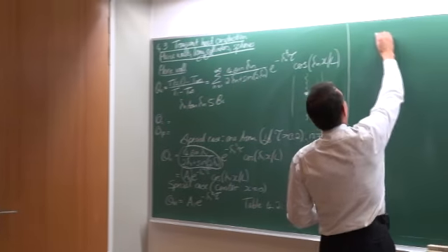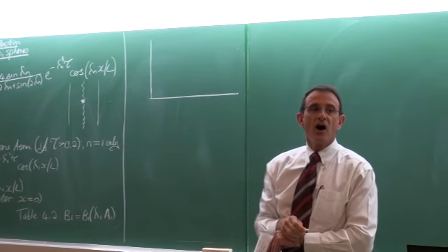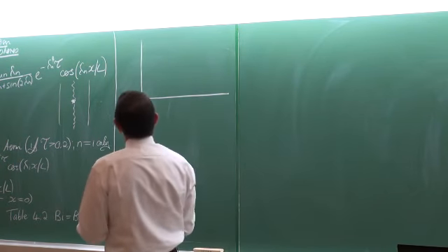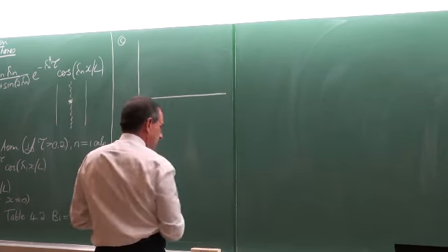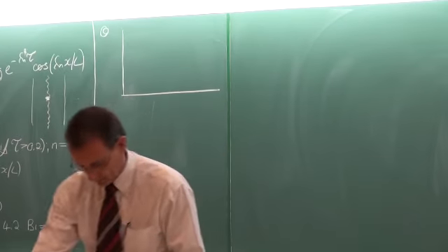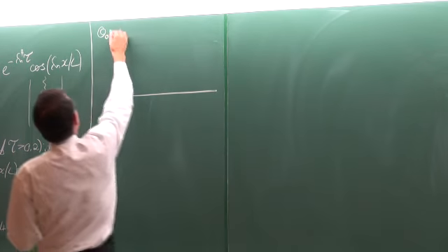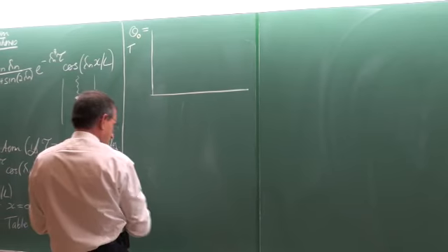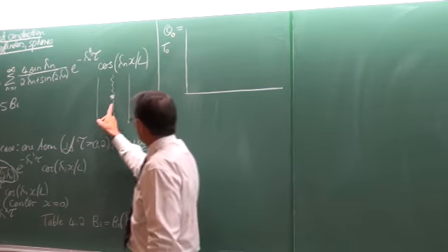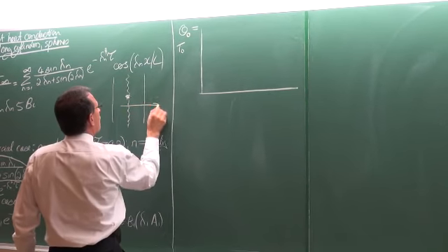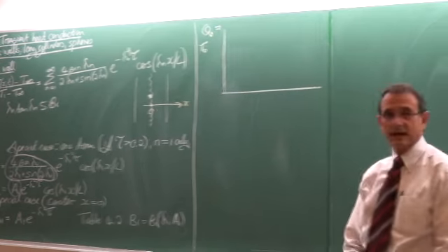There's another approach that we can follow, and that is the so-called graphical approach. With the graphical approach, it's called the Heisler charts. And with the Heisler charts, here we've got theta 0. Theta 0 would mean it is equal to the temperature 0. What does that 0 mean? It means where x is equal to 0. So on this coordinate system, x equals 0 would be that point there. So it's on the mid-plane.